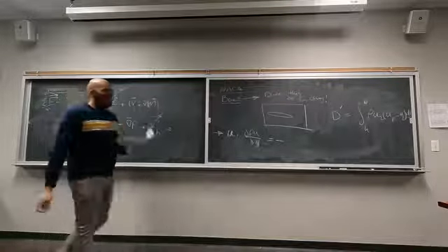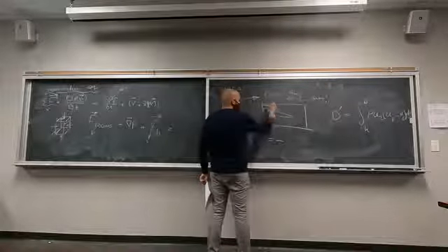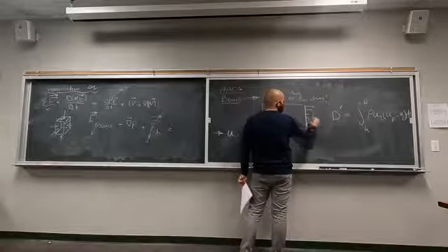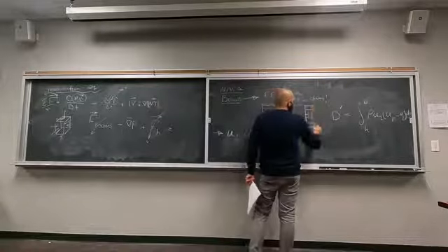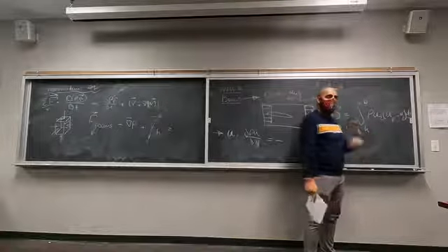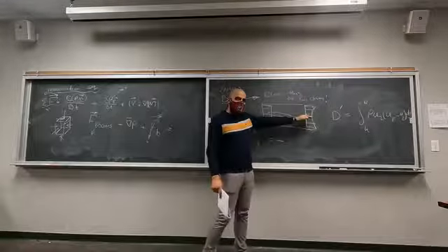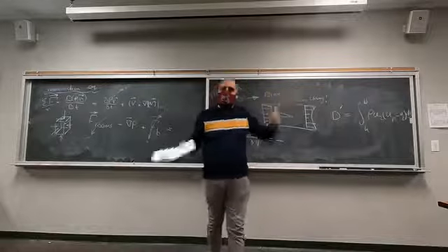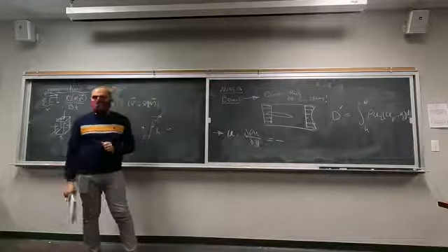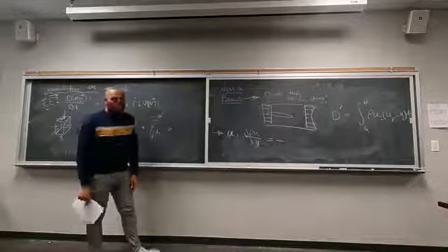So what does this equation tell us? As long as you can get the velocity distribution here, and you can get the velocity distribution here, this integral is going to give you the total momentum that has been lost to this airfoil in this direction, which is the drag force. This is the definition of the drag force. Any questions so far? Okay.